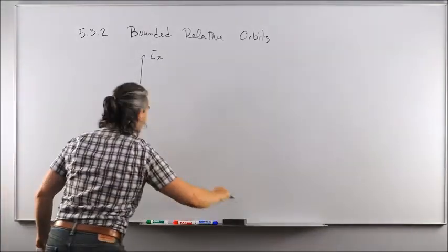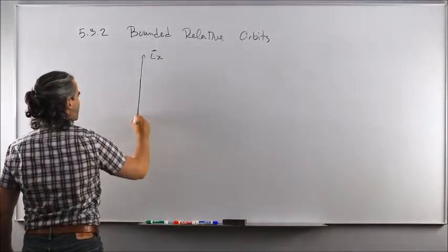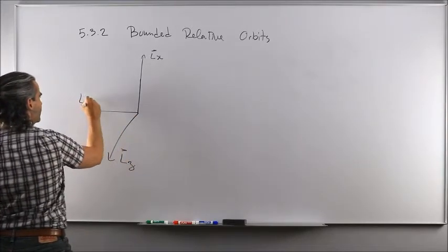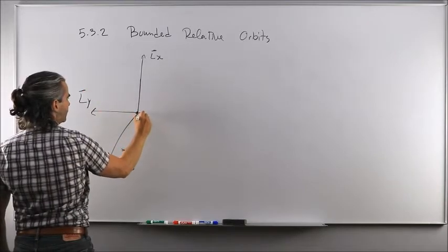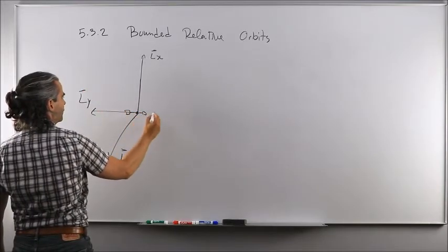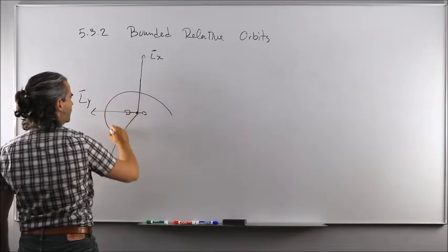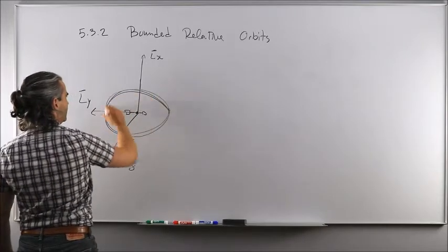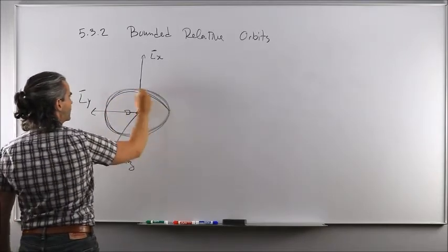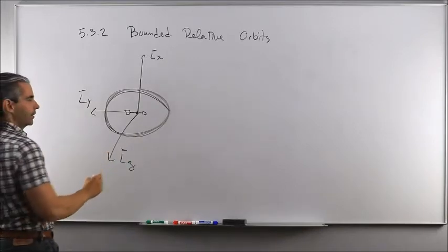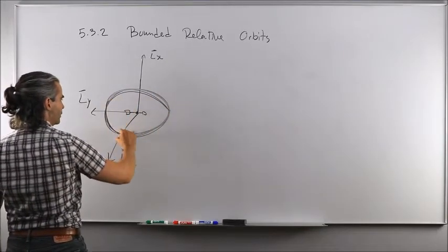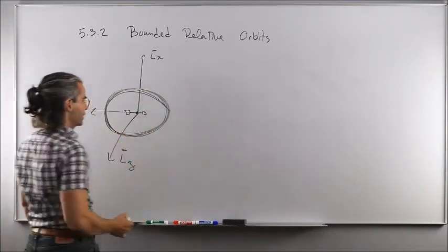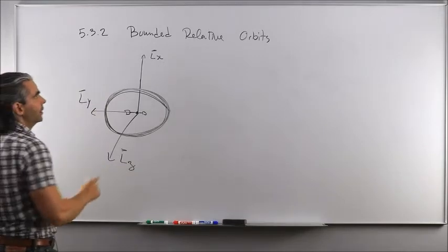that over multiple orbits of both spacecraft around the Earth, we would see in terms of relative motion in LVLH, with the target always at the origin of LVLH. We would like to see something that does this and then repeats itself, okay? Such that both spacecraft always stay in the vicinity of one another and that the relative motion is bounded, okay? It doesn't go unstable, or in other words, it doesn't drift indefinitely. This is good design. So how can we do it?